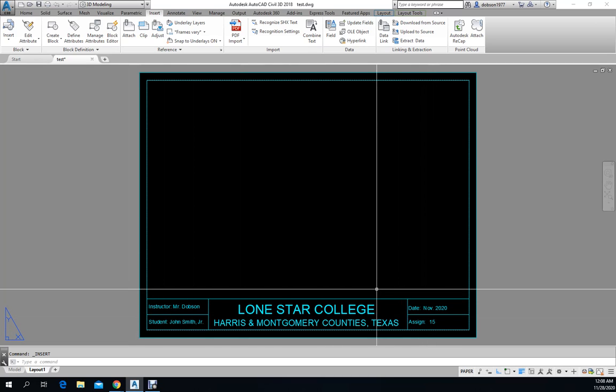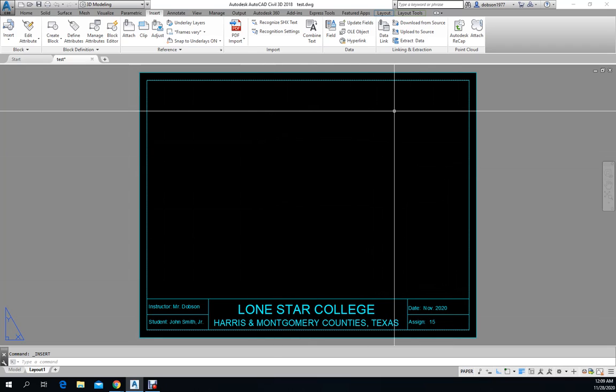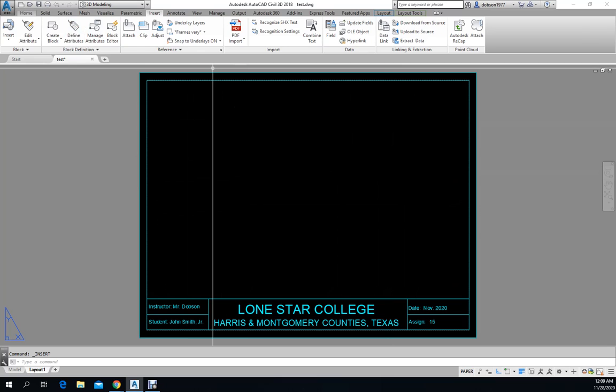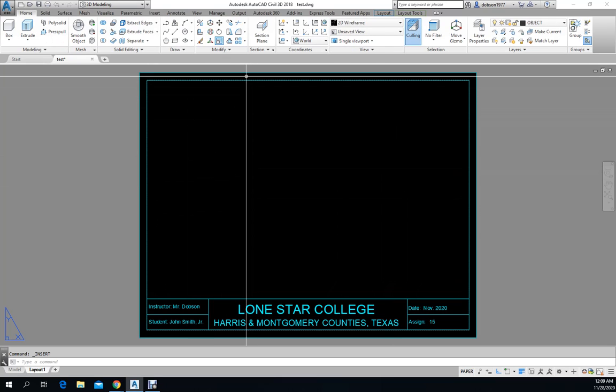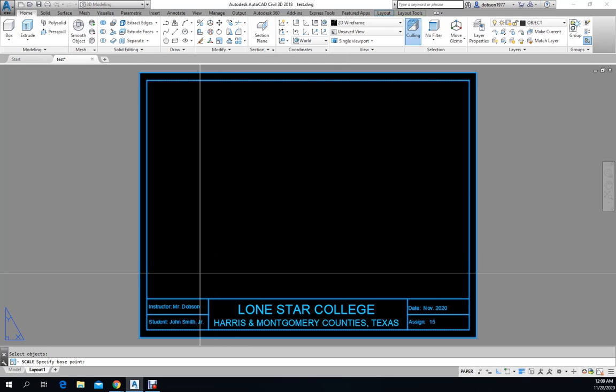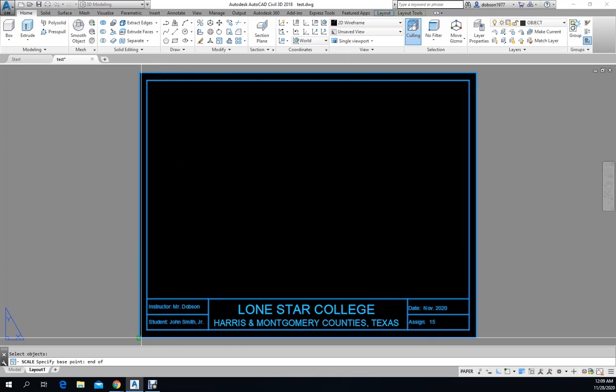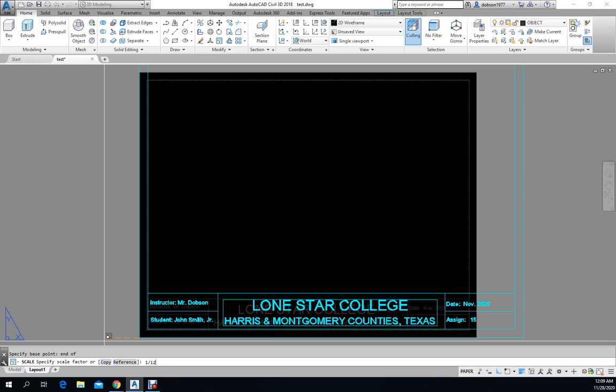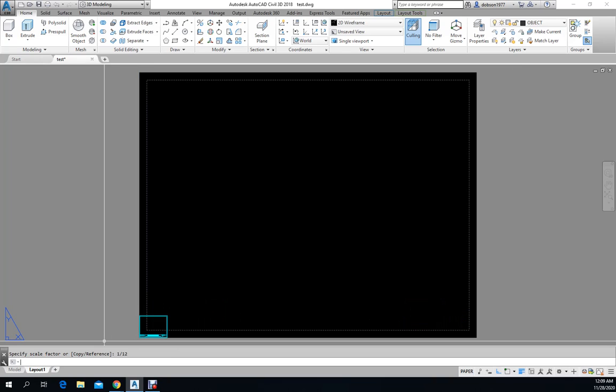Okay, now just to kind of show you, and this is pretty much the end of the video, but I do want to show you what happened. I'm going to go to scale, and I'm going to pick this title block, and I want to pick the base point right here in this corner because that's 0,0, and I'm going to type in 1/12, as you can see down on my command line, and I'm going to hit enter. And that's what I had a few minutes ago when I did it incorrectly.